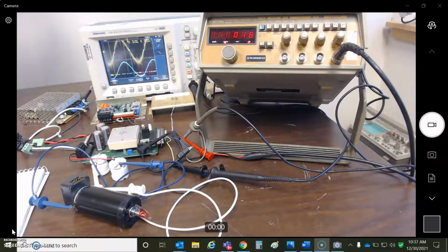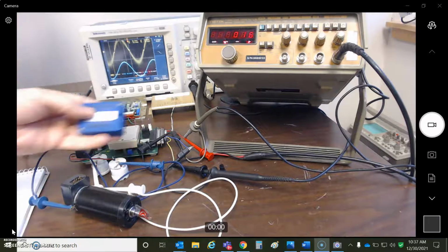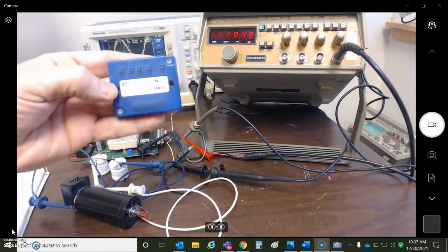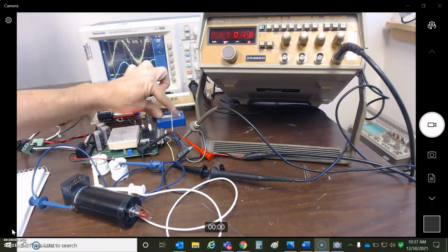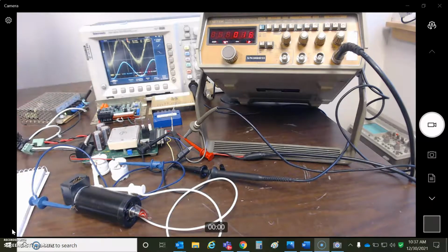So today we're going to look at the crossover distortion on a PWM amplifier. I'm going to use the Bantam here, and this is a small drive that's used to replace a lot of the older, like 4000 series or 400 series in current mode, or even a 503 with Halls doing trapezoidal commutation. It's much smaller, and it's got a goodly amount of current.